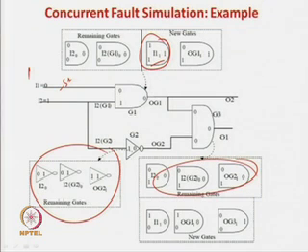Now, you see, this is a new fault. Previously, if you remember, we were applying 1 1 and the answer was a 1, so we were detecting a stuck at 0 fault. Now, because you are changing the value from 1 1 to 0 1, obviously the answer here is a 0. So obviously a stuck at 1 fault at OG1 will be added over here. In this case it is 0 0 0 1, but here instead of 0 the answer is 1.